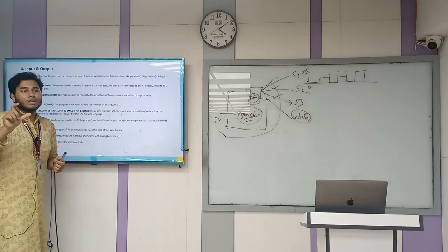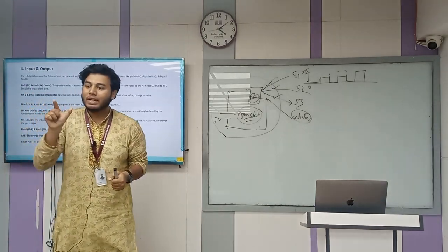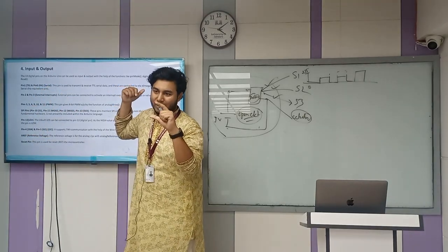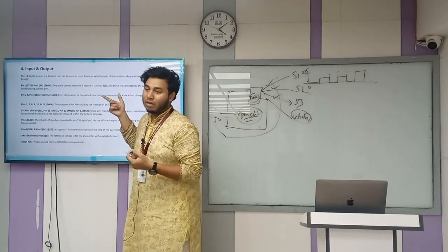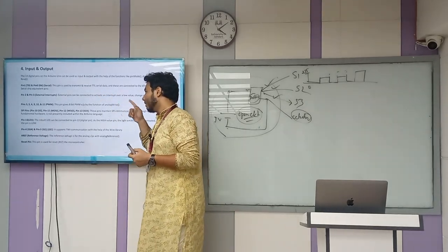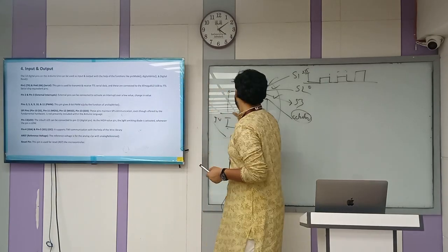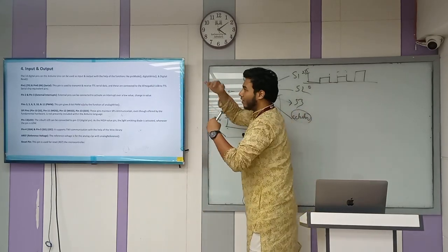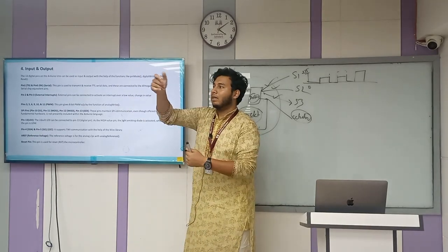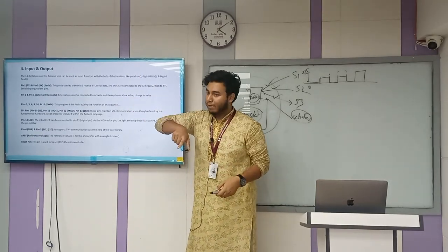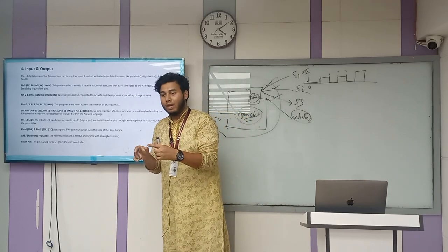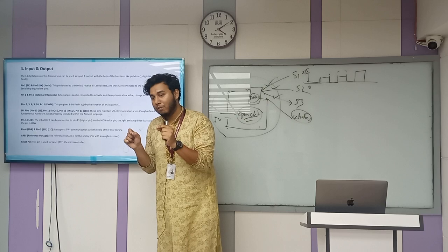Why 8-bit? Because your MCU can operate 8 bits at a time. We have already seen that this MCU, the ATmega328P, can operate on 8-bit PWM pins. So those bits define the duty cycle range for that particular converter. At a particular time, 8 bits can be operated on the basis of a 0 to 255 range. Basically, those are the analog values.